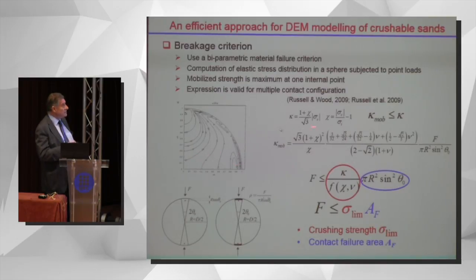So this computation gives rise to this expression, which actually can be grouped in two parts. This first part is a stress, which depends only on the properties of the material forming the particle. So this is a kind of limit stress. And the second part refers to the contact failure area for this particular case. So it's the product of these two which actually gives us the criterion to check whether a particle will break or not.